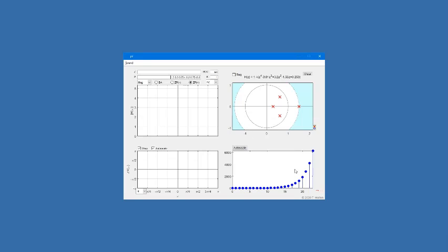The impulse response is monotonically increasing, and since it's unstable, nothing is shown for the magnitude or phase of the DTFT. We can change the region of convergence by putting another value in the box here, for example, 0. This is now an unstable left-sided system, and the magnitude and phase are again not shown.